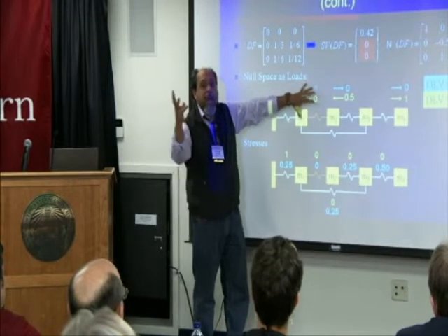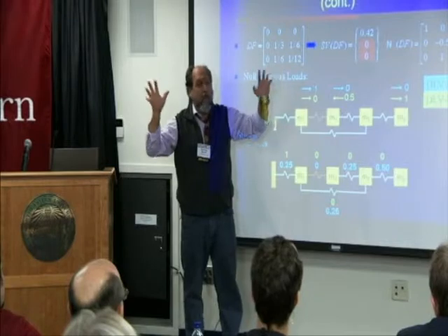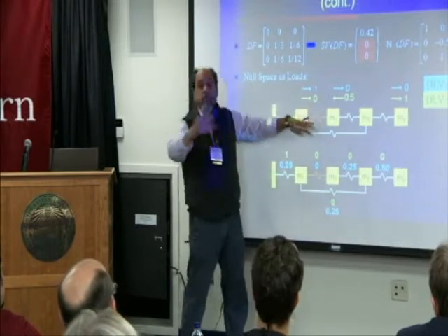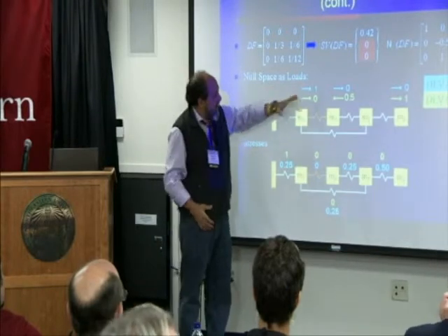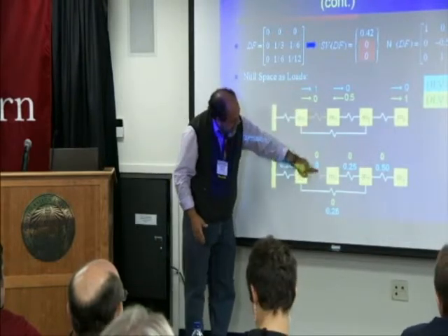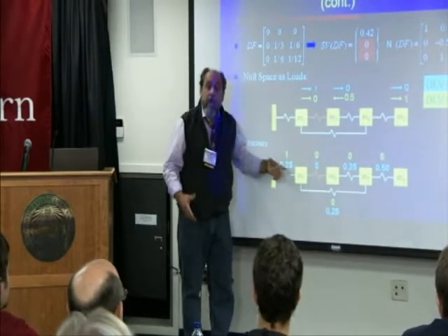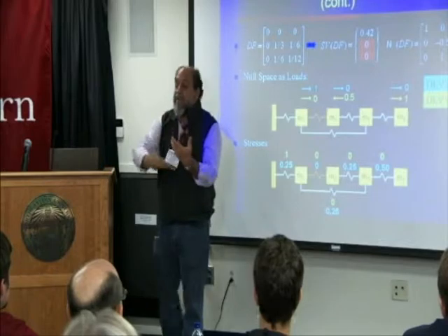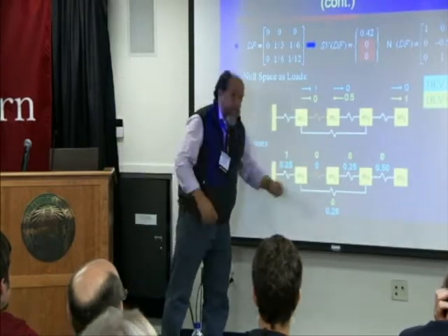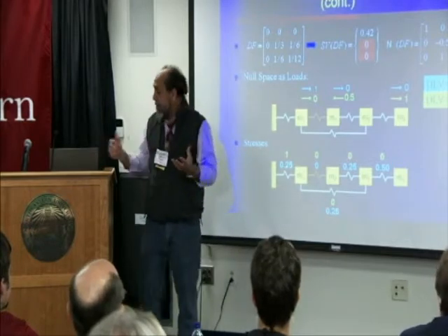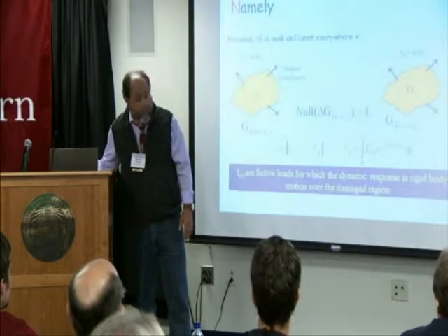At this point, we have to have a model. The computation of the loads is model independent, but the computation of the stress field that says where the damage is, of course, requires a model of the original system. The stress field is computed, and as you can see, it is 0 over the only part of the domain where there's been a change. In other words, it's bypassed. It's gone around. For that load, the change in this spring is entirely unobservable. Okay, so we would say the damage is on the spring with the zeros.